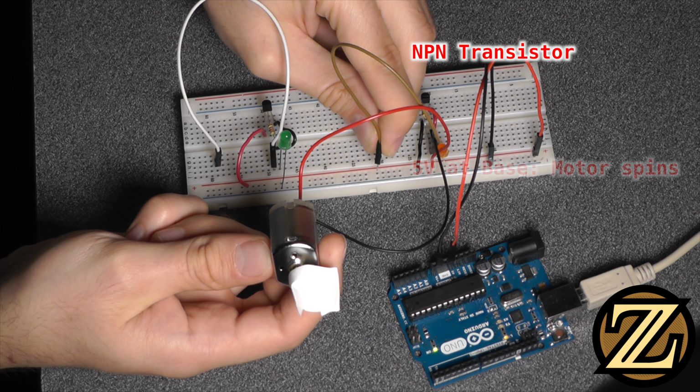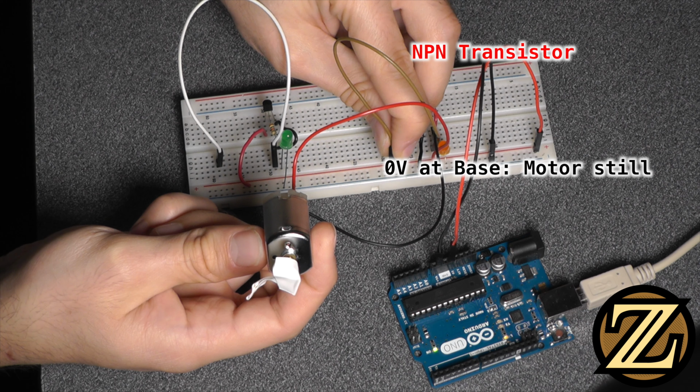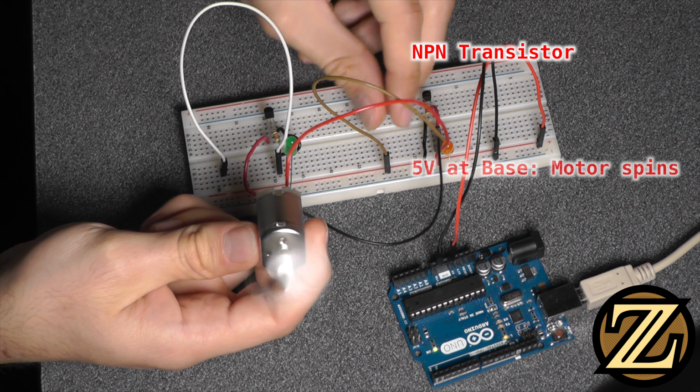Here I've built up two demo circuits using both types of transistor. On the right is the NPN transistor. When I apply 5 volts to the base, the motor starts to spin. When I remove 5 volts, the motor shuts off. When I apply 0 volts to the base, the motor stays still, and again 5 volts turns it on.